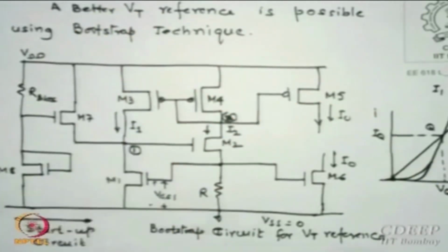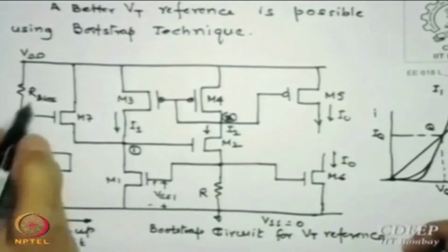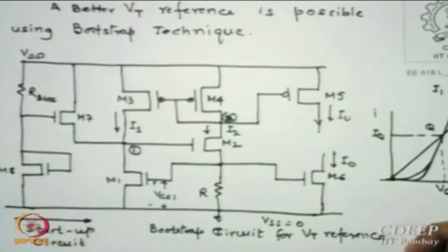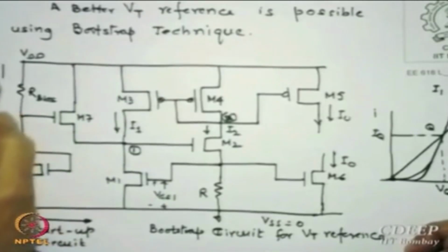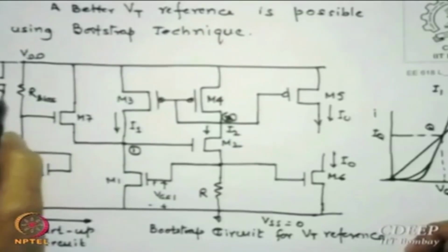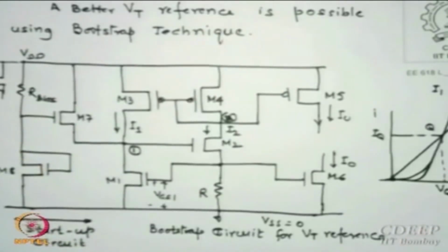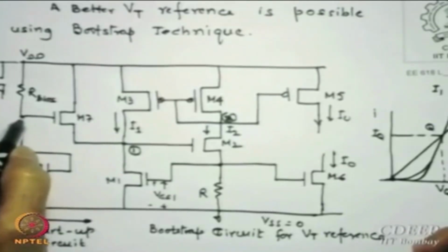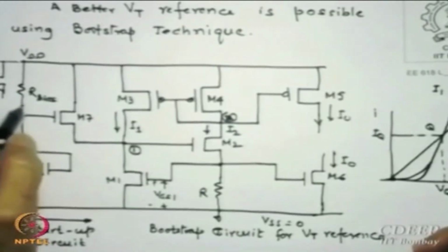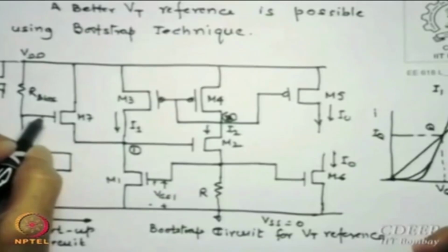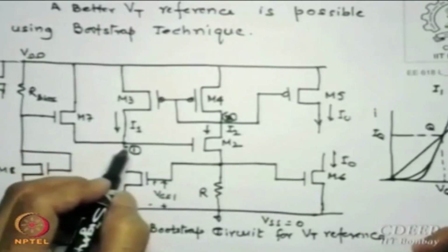Now if this is at 0, when the startup starts, the way the startup circuit is, this is R bias, this also can be replaced by what? I can always replace this like this, okay, it is a diode. Essentially I am making a diode drop, VDD minus diode drop. Okay. So there is some potential which is smaller than VDD, but I am adjusting that so that this one diode drop gets me VGS here. This potential is 0 now, is that okay?